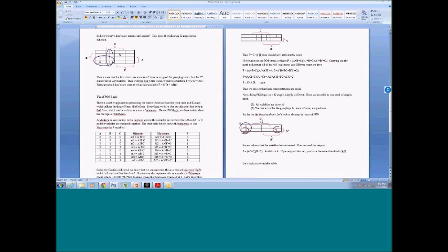Students just get the feel, they understand K-maps. They're like, okay, let's just screw everything up and really mess with them a little bit. So usually I don't do this a lot, but I will give them an exercise. Circle all the zeros using the POS logic, write that expression out, go through and do all the SOP logic with all the ones, and show that those things are equal.